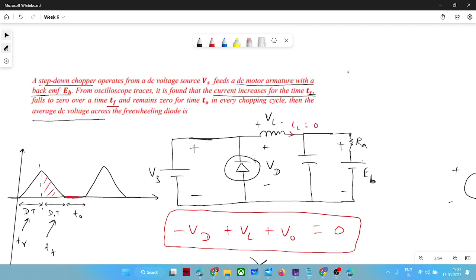See, during discontinuous conduction mode, this period comes. So it doesn't mean that it is open. You cannot say that it is a cap. If it would have been a capacitor, then you could have called it open. But an inductor is not treated in that way.